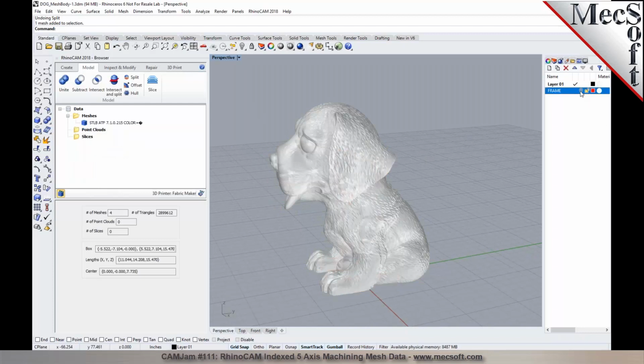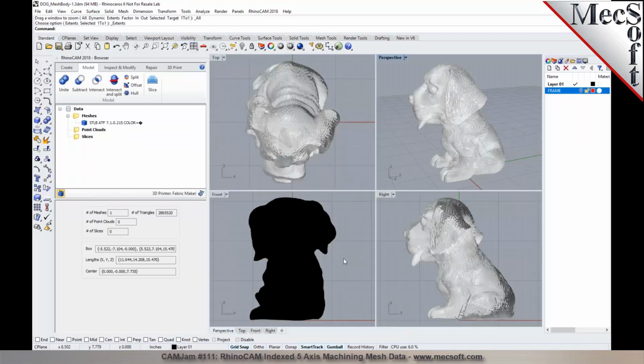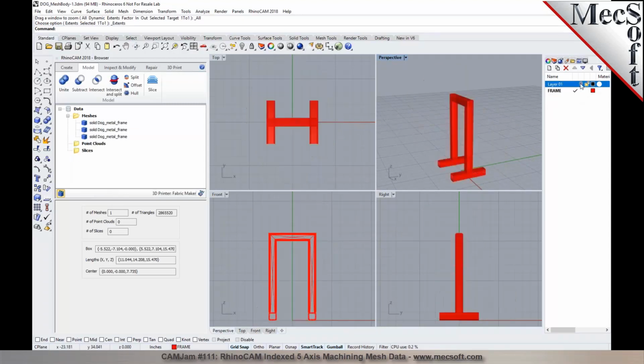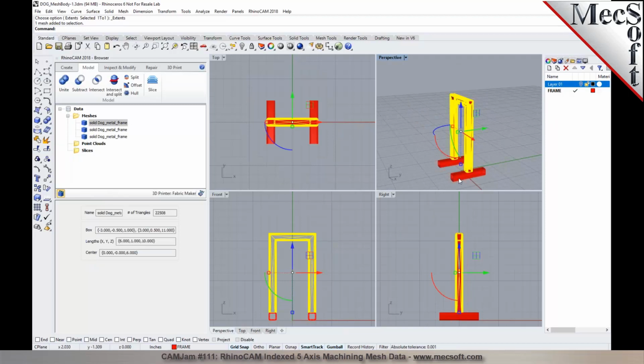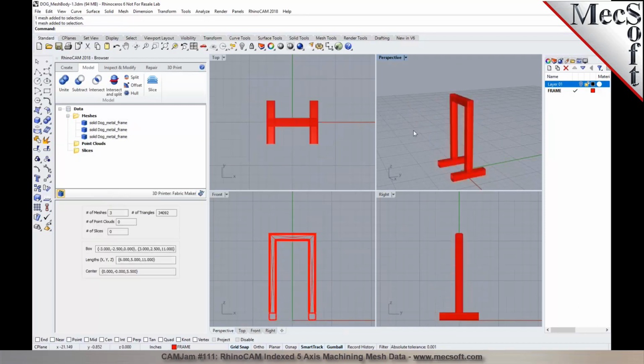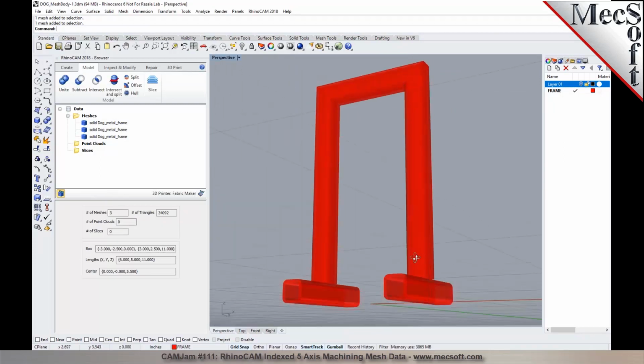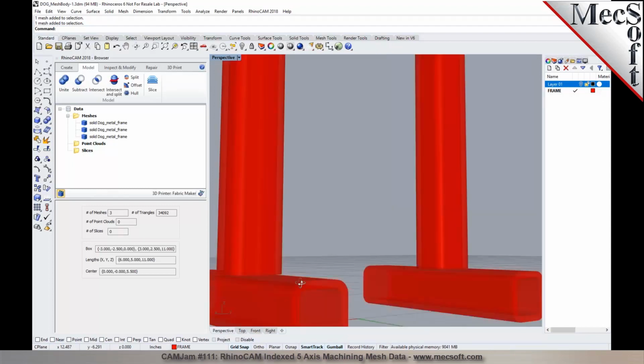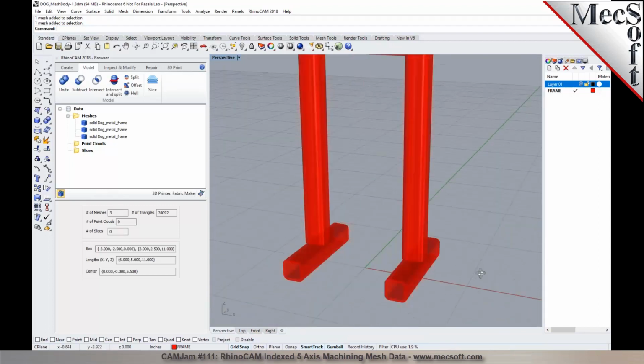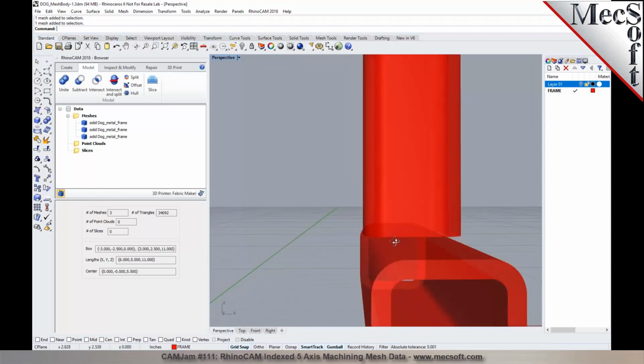Yeah. Okay, now let's go ahead and, as a workflow mindset here, we would probably start by subtracting the frame from the part, right? And then splitting the dog different ways, right? Yes, we could do that. So the frame first needs to be one entity, so I would select these and make sure it is all merged together, right? Yeah. You want to see if there are any gaps in here, and if they're not combined, we would have to merge them.